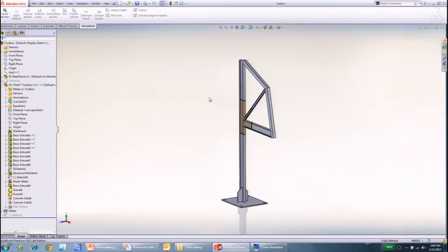So submodeling, if you look at literature, will say, okay, take the beam model, very coarse line model, and I'll identify an area, and then I will actually build the joint details in the submodel. So that was a textbook case. Because of our compatibility mesh, you'll see that in one of the line items in the limitations, when you use a beam mesh, it merges all the nodes to make it one. So at this stage, we haven't supported that yet. So that's going to be a limitation, but I'm going to show you a workaround for that.